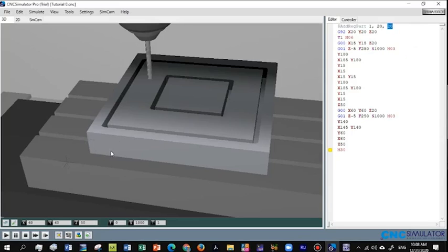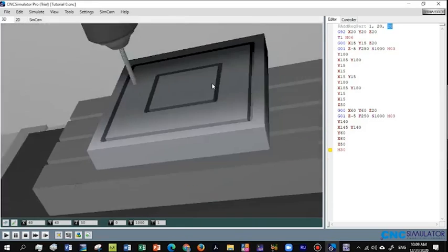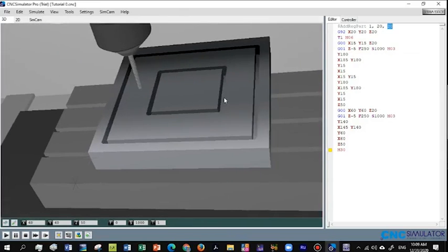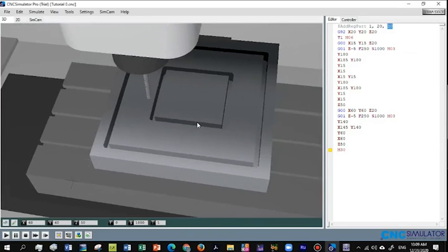It's okay, but where you place it, you need to consider during your writing of the coordinates. Then I define the tool that you are going to use. As you can see here, the shape is all lines. So we are going to use linear profiling here, no circular profiling, and also no drill. We just need to define the coordinates. So we are going to use G01 here. You can see G00 for the fast traverse, and G01 for the linear.